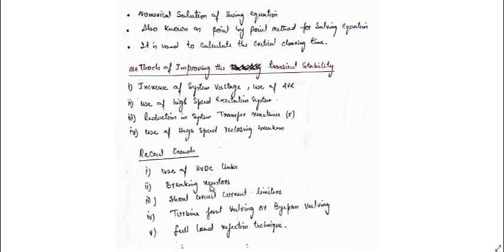They are usually connected in neutral of the generator. Whenever the unbalanced fault occurs, the current flows through this. Since they are resistors, they result in the power loss, and the power loss will be in the form of electrical power. Electrical power has increased, so that the total accelerating power, that is Pm minus Pe, will decrease. So when accelerating power decreases, the chance of stability will increase.